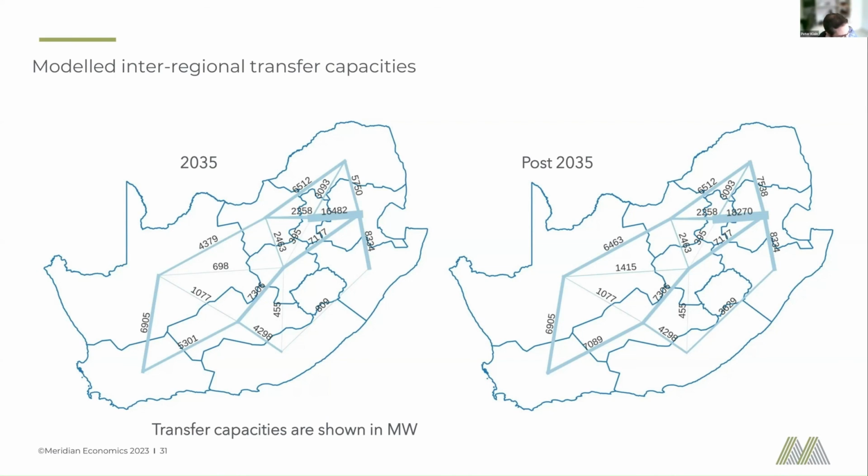Yeah, so it's not coded in at the moment. If you wanted to, so you say, for example, I have a certain amount of spinning reserve based on dispatchable capacity in a region. That's not coded in at the moment, but it's definitely something that's quite easy to do with the custom constraints. So with LinoPy, you can basically pull in any kind of variable and you can group different technologies, and you can say at each bus, there must be a certain amount of reserve capacity.